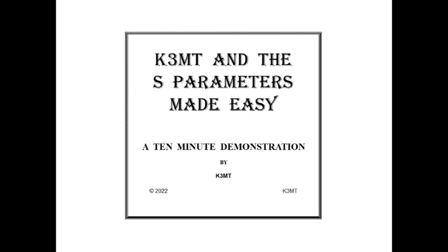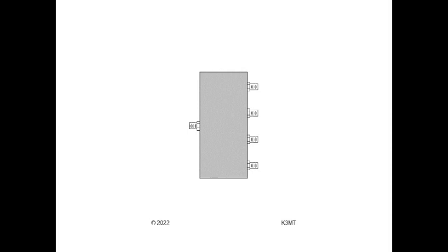Let's start with a 1 to 4-way splitter, used to distribute a cable TV feed to 4 rooms of a house. These have 5 type F coax fittings, called ports. They're 5-port networks, used on a TV coaxial cable system. With a 75 ohm load on each output, they present a 75 ohm load at the input port. To work properly, the loads are needed.